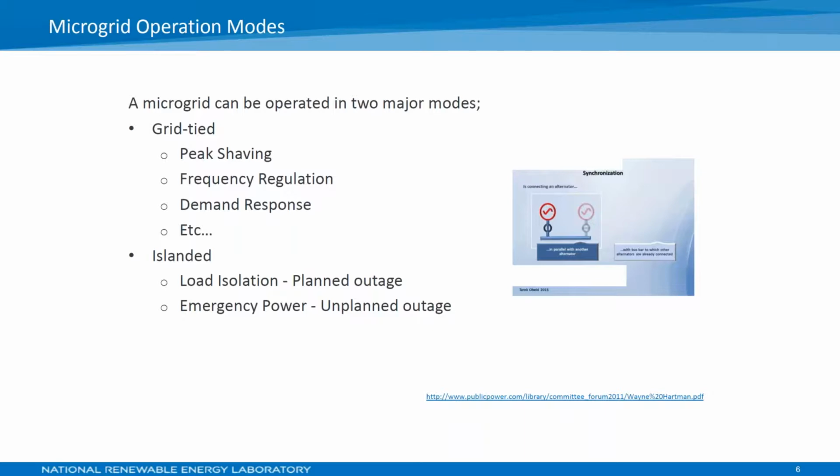The electric grid's a big balancing act, and your generation can participate in those markets to help balance the frequency of the regional system or even the larger interconnect, like the Western interconnect or the Eastern interconnect. Demand response, again, you can serve as support to your local electric utility by turning off lights and other heavy loads, which could then help reduce your utility rate, or the utility may actually pay you to participate in this demand response. And then isolated mode or islanded mode is the area where up in Alaska, they're experts in operating in islanded mode.